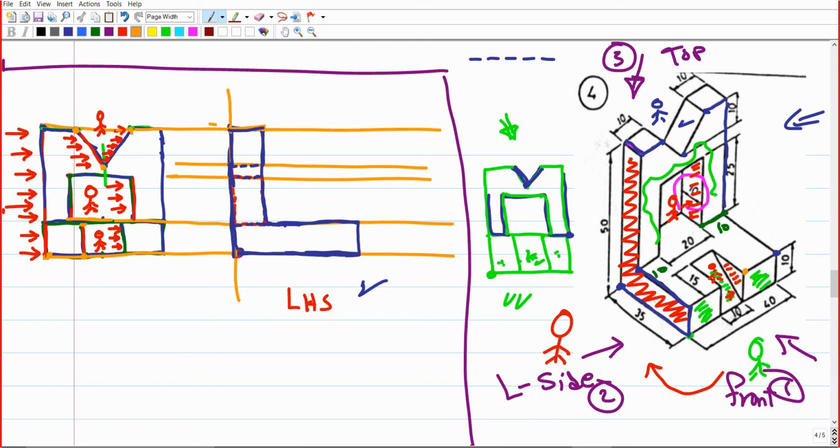So if I ask you to draw it, you need one corner like this one, which should coincide with this edge, to this point. So from this point, if you draw a line, the length of this line should be 15. Do you see this one? So I'm going to draw a line of 15, but this line should be dash. So dash over solid will be solid. Then you're going to end up with 1 point here.